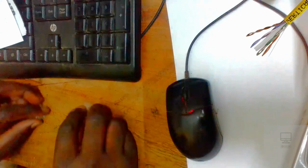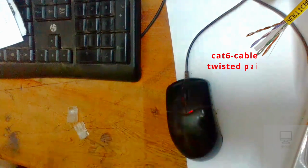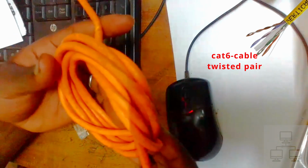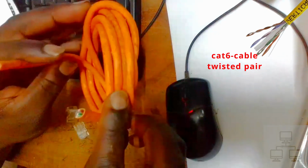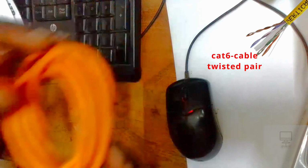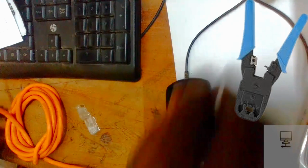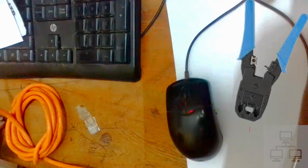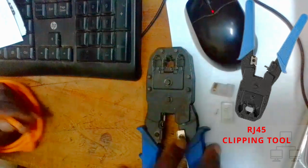And with me I have RJs, and RJs come in different types, but today I've decided to use this one. It is a fully plastic RJ, with no way through for the cables, it is blocked in front. So we are going to terminate it using this Cat 6 cable. It is a twisted pair, and it is nice for noise cancellation and better transfer of data.